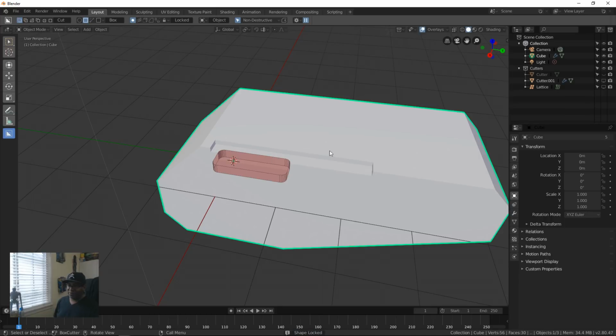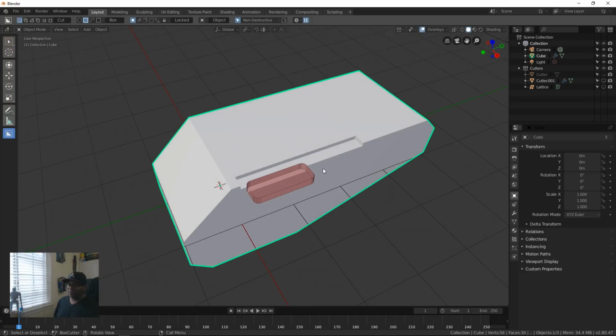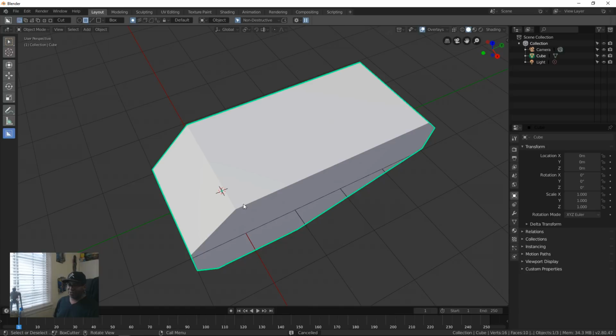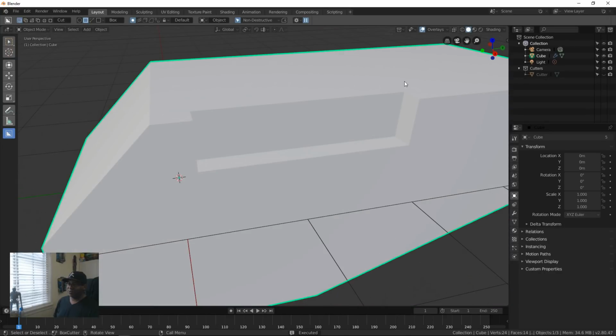And before I drop it, there are two things that you should probably know. In Blender, using this workflow, there are going to be some things that are destructive and non-destructive, excuse me. So I'm going to back up really quick and show you. I'll escape that and go back one. So if I just hold Control, red box this, go down, and cut, that would be a destructive cut, because the box is no longer live.